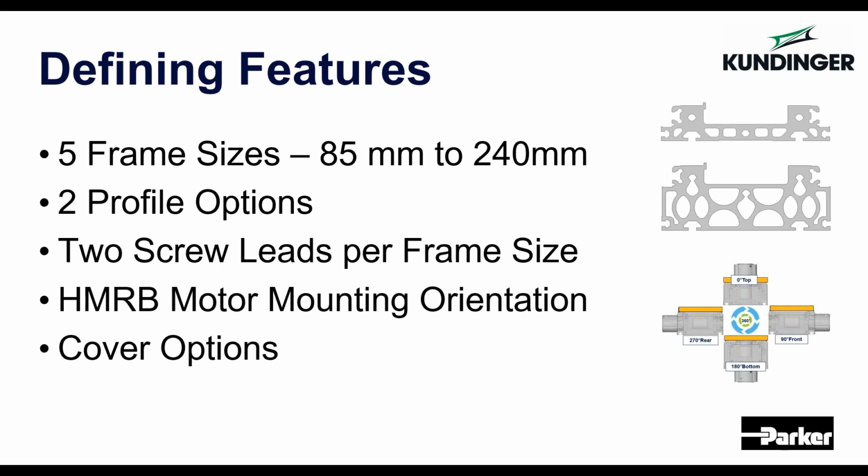And the motor, the 270 and 90 options where the motors come out to the side, those are actually field changeable. So the actuator will come with universal end blocks that have provisions for moving your motor mount and coupling housing to either side of the actuator, being the drive side, the side you got it on.